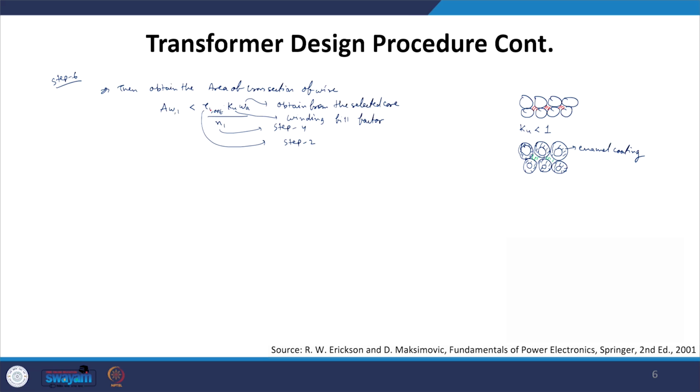So that is why gamma 1 optimum Ku and Wa is the area which is taken up by winding number 1, and this has to be greater than or equal to the number of turns multiplied by the area taken up by the individual wire, then only can we accommodate that many turns in the allotted area in that particular window of that particular transformer.